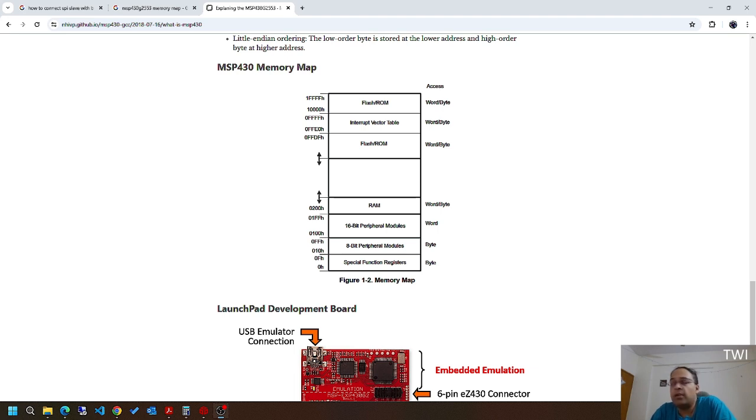Now there are two ways to do it. One is to use the normal bootloader, and you can invoke the bootloader in multiple ways. These are out of scope of this video, because it requires a detailed study of the controller and the architecture you're using. If you're using a Linux platform, it will have its own GRUB bootloader or some lower version of U-Boot. An RTOS can also have its own bootloader environment, but the main thing is that there has to be a bootloader.